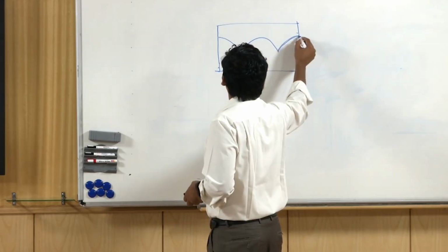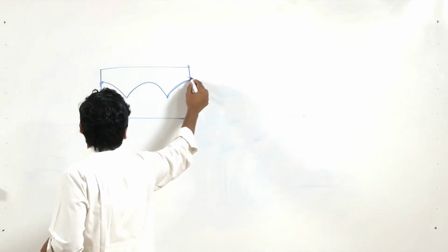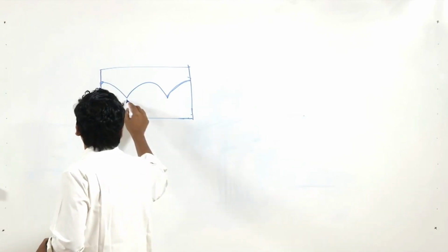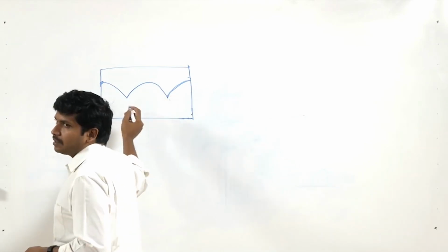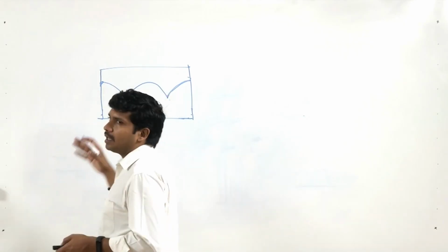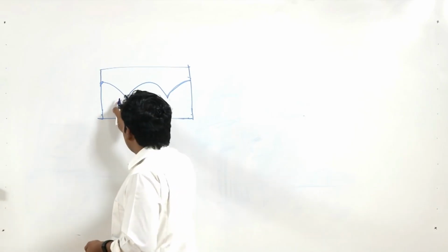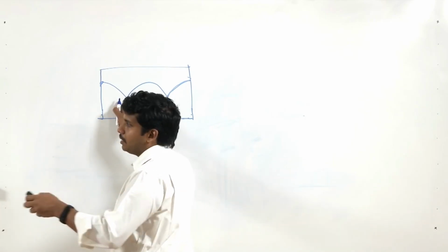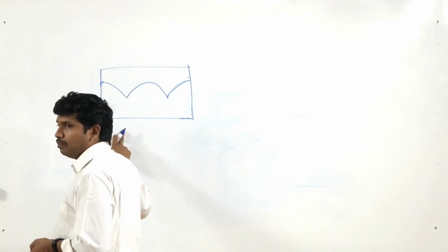Just take a cross section, you find that there is a source here and there is the other wall surface. You have this particular wave phenomenon which is forming. It will actually disturb. This is a kind of resonant thing where it will not allow normal decay of sound, it will persist. The sound will not decay as anticipated in your reverberation time calculation. RT will not tell you whether you will have room mode or not.